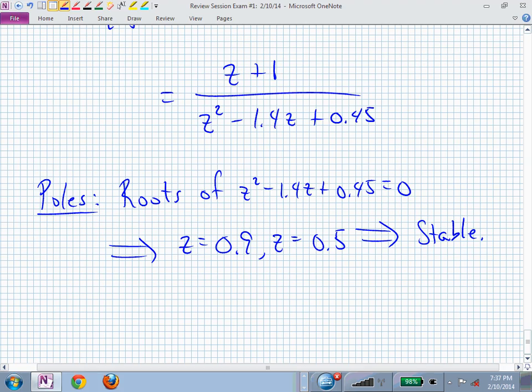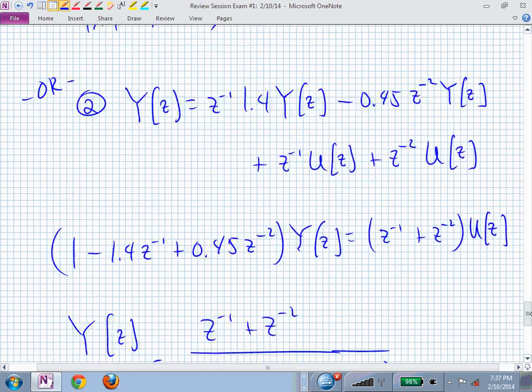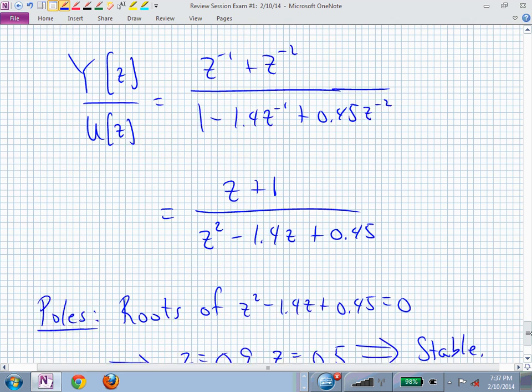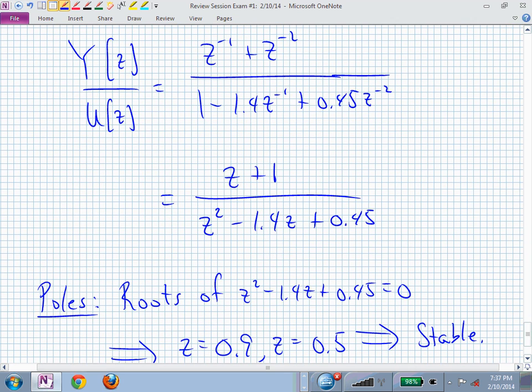Yes? So why do we not have to worry about the region of convergence in this particular problem? The region of convergence, we were viewing that as waveforms. Now it's a little bit subtle, but now we're talking about a system. If you go back and think about Laplace, 1 over s could mean 2 different things.